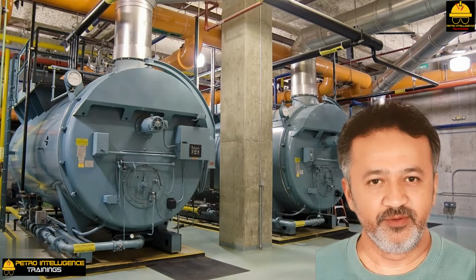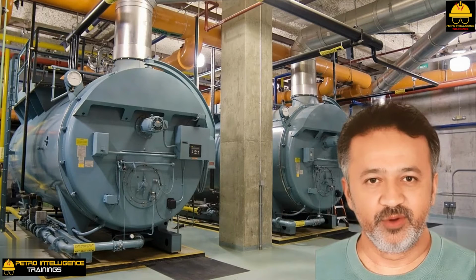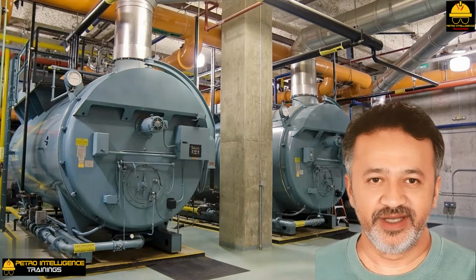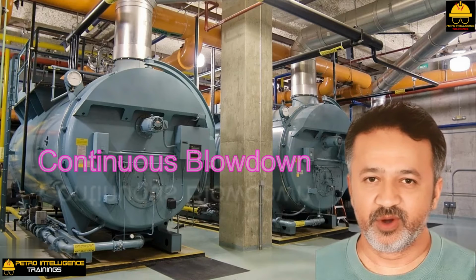Two types of blowdown from a boiler are used: continuous blowdown from the steam drum and intermittent blowdown from the mud drum. Both will reduce silica. Note that with the continuous blowdown, heat recovery equipment may be economically justified. Continuous blowdown. This blowdown water is best not drained from the very bottom of the steam drum.